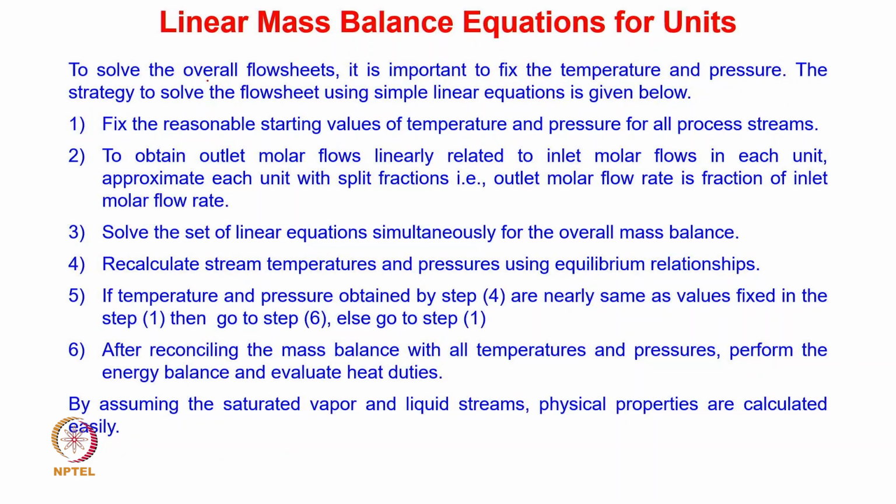To solve the overall flow sheet, it is important to fix the temperature and pressure, and the strategy here is to obtain the linear set of equations. For that, the different steps are given. The first step is to fix reasonable starting values of temperature and pressure of all process streams. So first we fix the temperature and pressure for all the process streams.